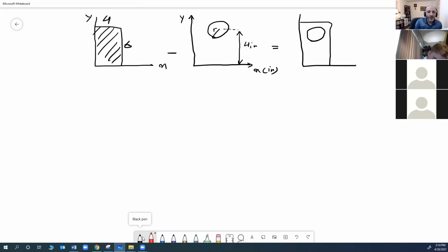So from a composite area, I can write I x minus I x equal this I x. This is for area 1. I honestly don't know which way to put the 1. You can say I1x or Ix1. It just means area 1, area 2. Okay, area 1, area 2, and this area. This is from composite area. From the parallel axis theorem,